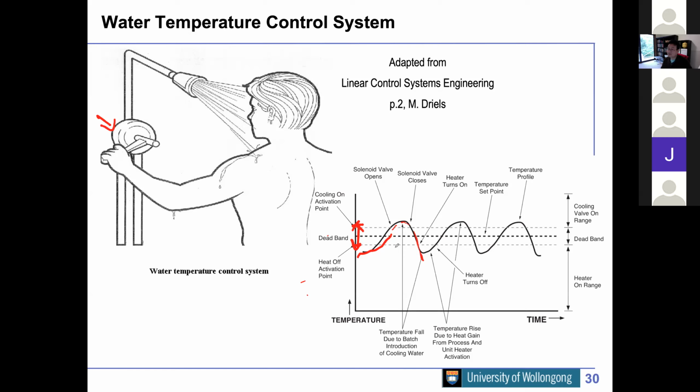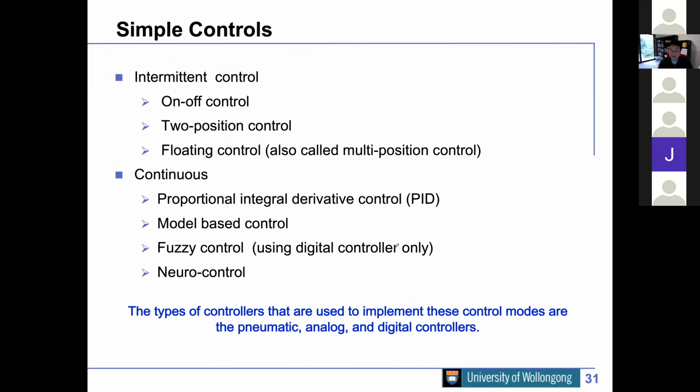In that situation, PID control will become quite hard to do because you can't really tune your control signal up and down. Your control signal only has an on-off state. If you do PID control, you might end up switching that thing on and off very frequently and damage it. So in that case, we just do this on-off control and switch control. So let's look at that situation.